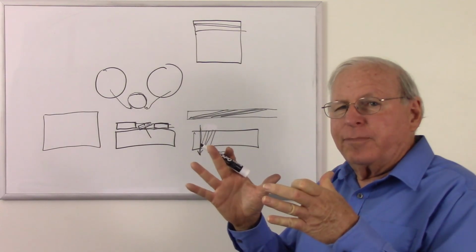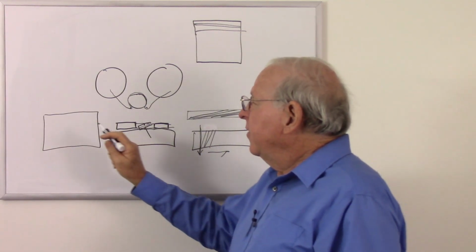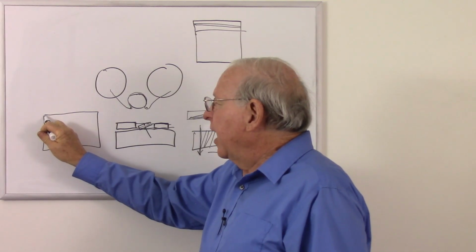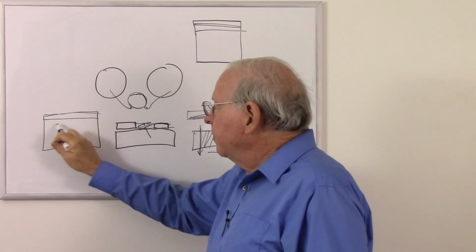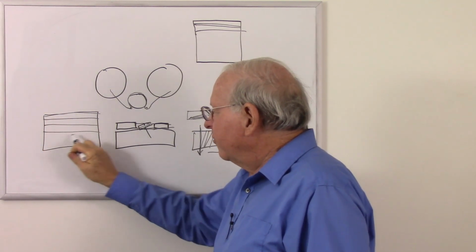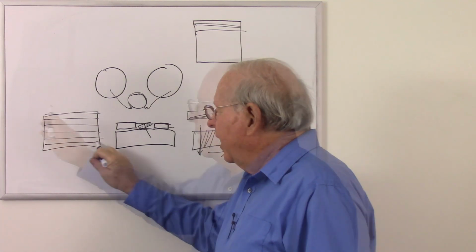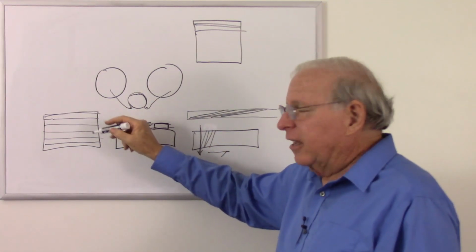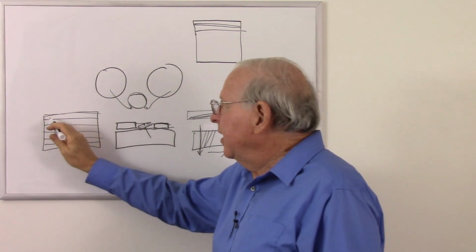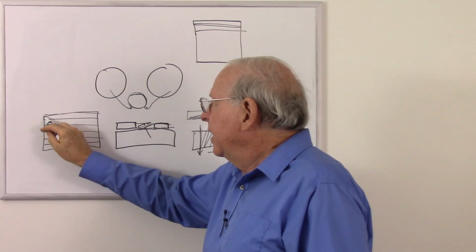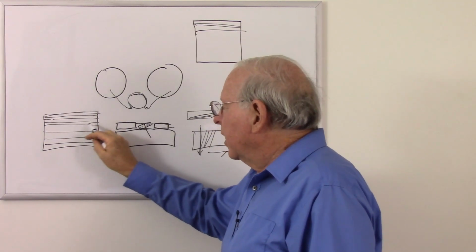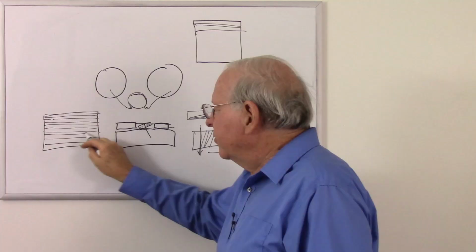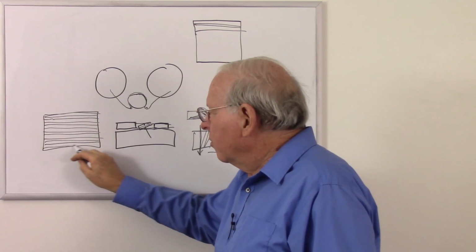To squeeze it into less space and then have more channels, they would first scan the odd numbered lines, exaggerating my size here of course, and do that in a 60th of a second, so it's half the information. Then they'd scan it again, the even numbered lines, once again taking a 60th of a second to go across the screen.